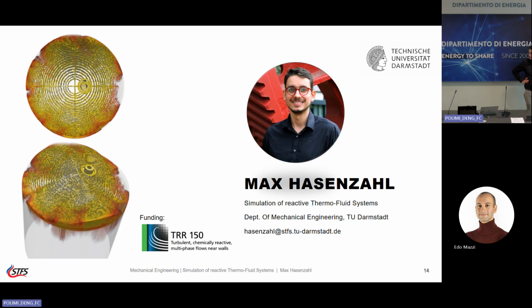Because if you're wrong by 30 degrees in the wall temperature, it probably will not affect the simulation, because that mostly is the viscosity in the near wall boundary layer for the motored cases. But if you include this in the end, in the non-dimensionalization, that makes more of a difference. I think that's something we need to think about sometimes, to make sure that we do this consistently.